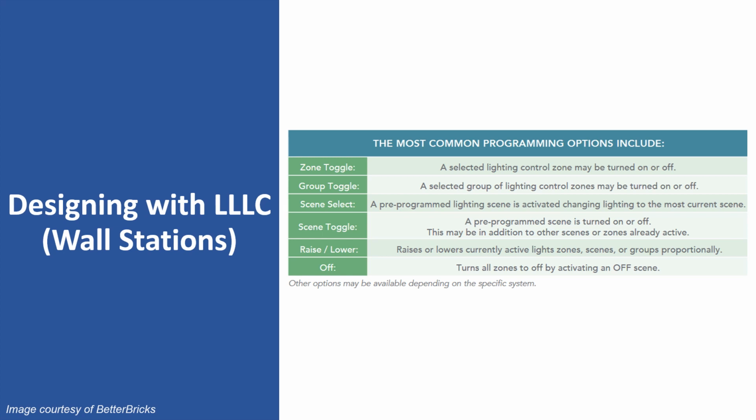Ideally, automatic control effects implemented by luminaire-level lighting control luminaires should be free from distraction to any users in the area. The most tangible interaction with the control system occurs at the manual control interface, the wall station, which may be wired or wireless. The wall station may provide users with a variety of interactions, such as the ability to override the system to off, choose the light level, select preset lighting scenes, or a combination of these functions. To encourage user satisfaction, the interface with the wall station should be intuitive and simple to operate, with consistent, easily understandable labeling.